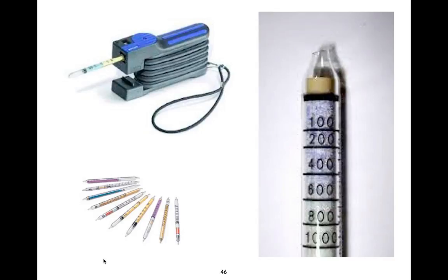Most of the reasons that you get carbon dioxide buildup inside of buildings is because people are breathing into the buildings. As you get people breathing into the buildings, the CO2 levels go up. Now, the only thing that'll take that out is dilution with outside air. So ASHRAE has worked out that if the levels indoors are more than 700 parts per million higher than the level outdoors, or say roughly higher than 1,000, that would suggest you're not getting sufficient exchange with outside air.